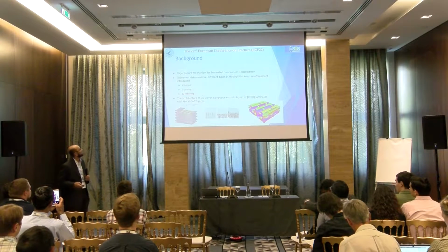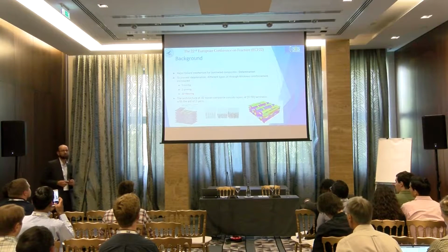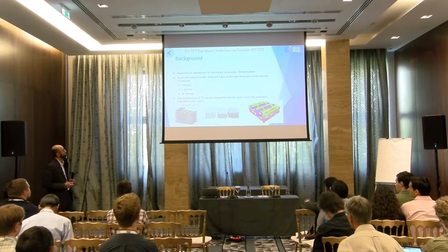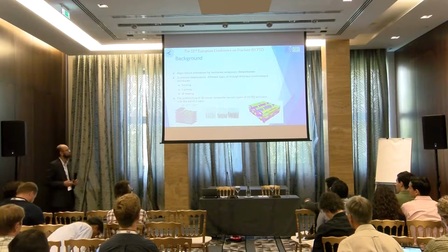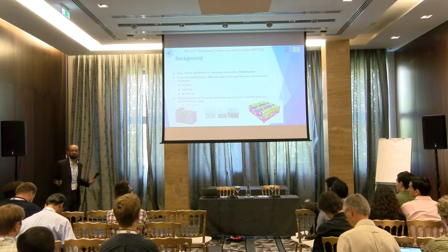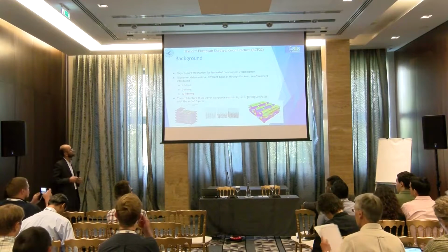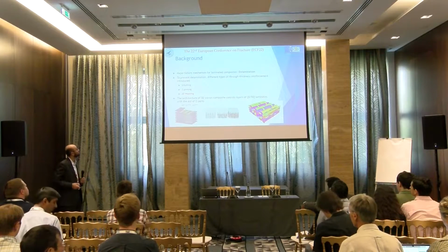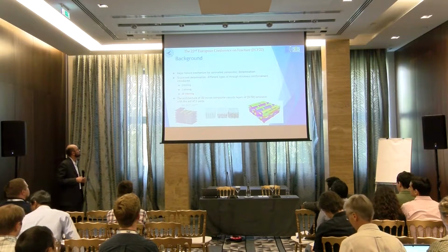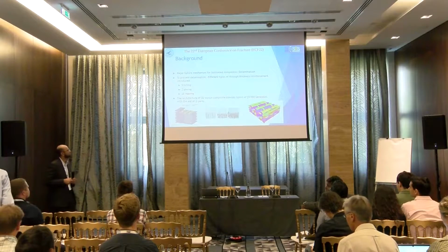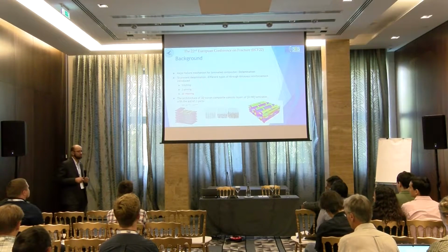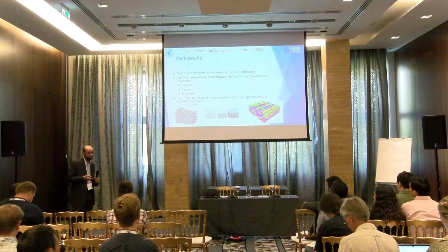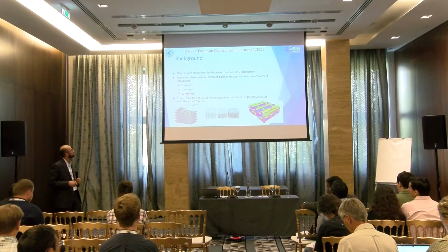At first, a little background. The major failure mechanism in composite laminated structures, which has been proved, is their delamination behavior. To control that delamination behavior, different methods have been used in the past, like stitching, Z-pinning, and 3D weaving, which will be the main emphasis in this presentation.